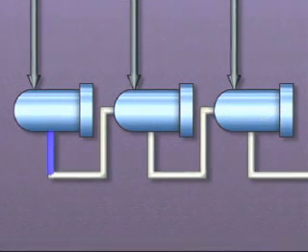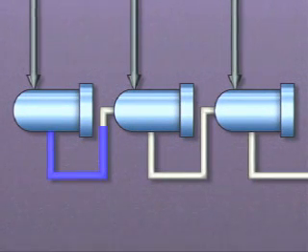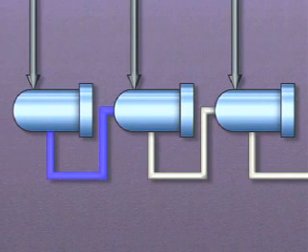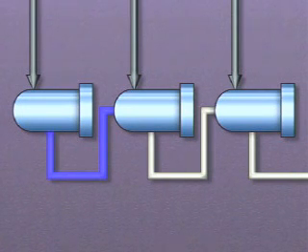That is, the drips flow through the normal drain line from one heater into the shell side of the next heater in the train. This heater has a lower temperature and a lower shell side pressure than the first heater has. The drips flash to steam because of the lower pressure within the heater's shell. The drips also mix with the extraction steam that's already in the shell. Thus, the drips are another source of heat to be transferred to the feedwater in the tube side of the heater.